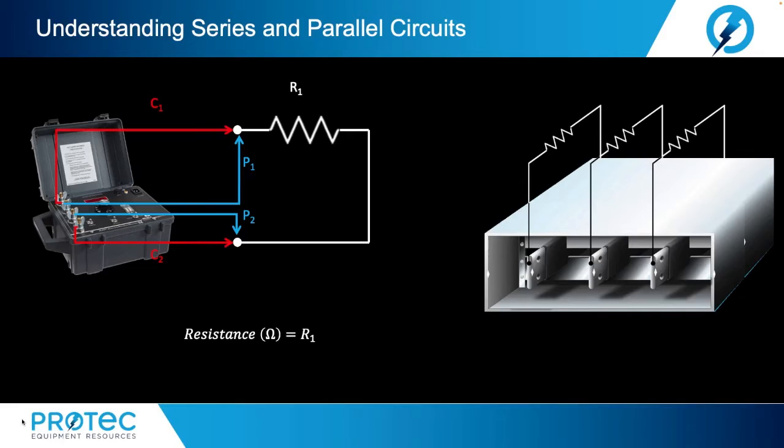So, let's take a look at actually performing the series test, or the continuity portion of the resistance test. Now here we would use a standard product like a micro-ohm meter, sometimes referred to as a DLRO, or digital low resistance ohm meter. Other terminology is a ductor. Now here it's a 4-terminal measurement. 2 of the connections are current in, followed by a return current, or current positive and current negative.